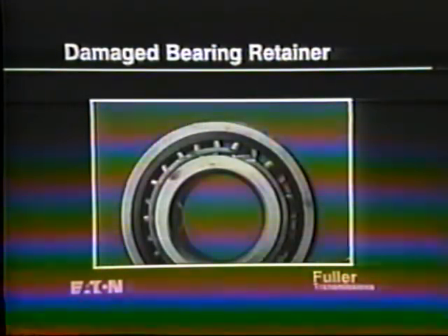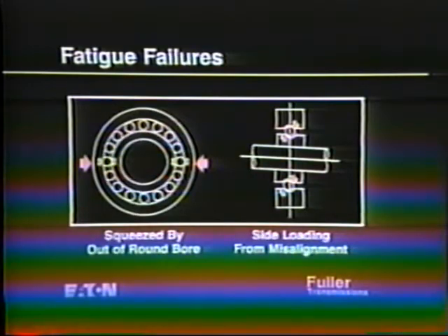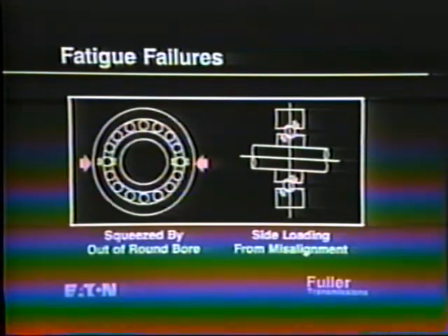Improper installation or removal techniques can also damage retainers, shields, or snap rings on the bearings. Bearings will fatigue after living out their expected life. This is normal after high mileage. Premature fatigue is generally caused by an improper re-sleeving of the transmission case bores, in which the bores are machined egg-shaped or off location. Out-of-round bores will squeeze the bearing races, causing an overload.